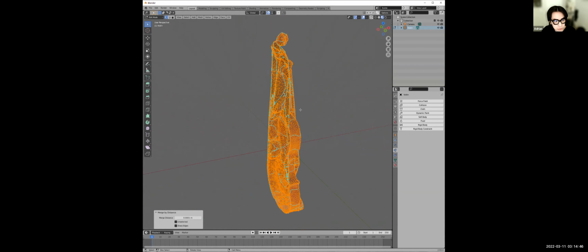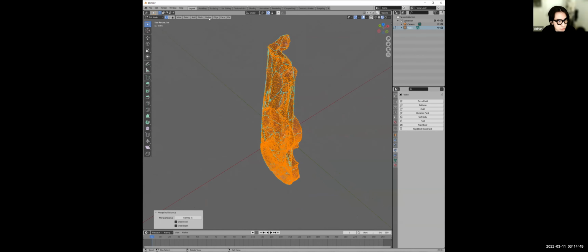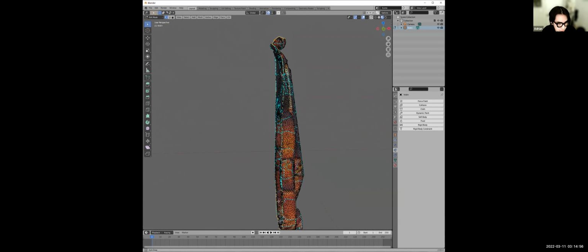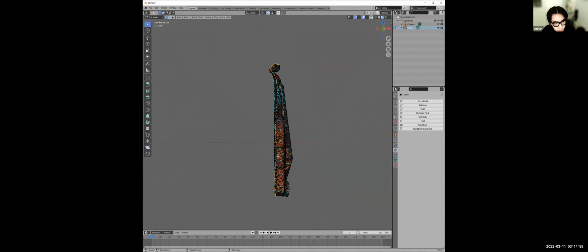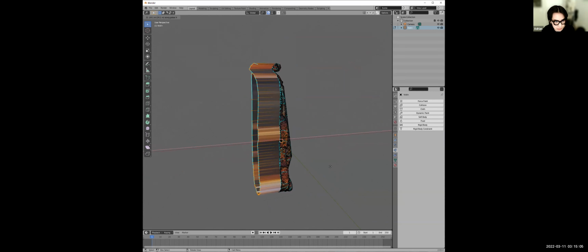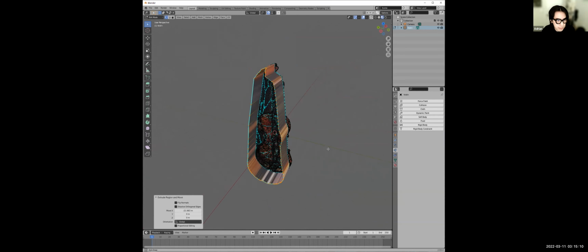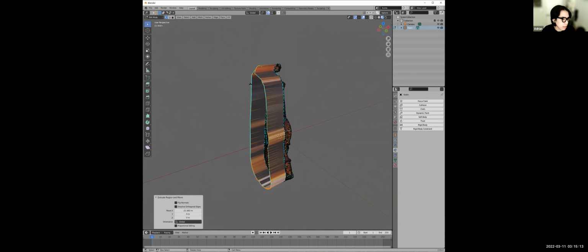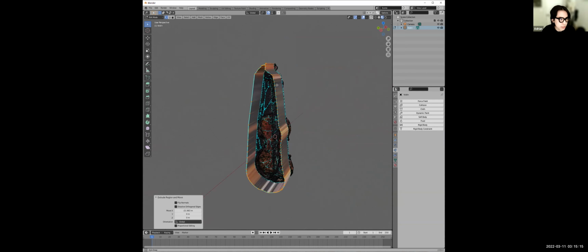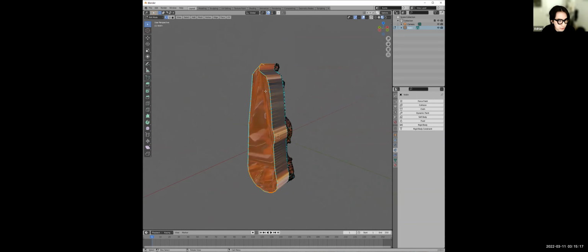And then the next thing we'll do is to close the back. We'll go to select the loops, select boundary loop, just select the open boundary. Hit E on your keyboard, E to extrude, hit X on your keyboard to lock it into the X direction, and then just drag it out as much as you want and left click to confirm. And then I think we've got the boundary loop selected. So we just hit F on the keyboard to fill.